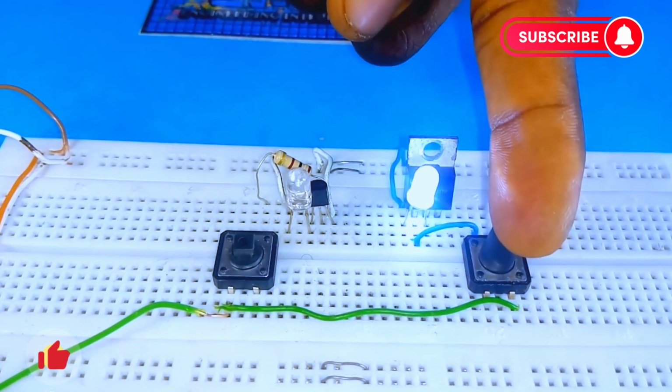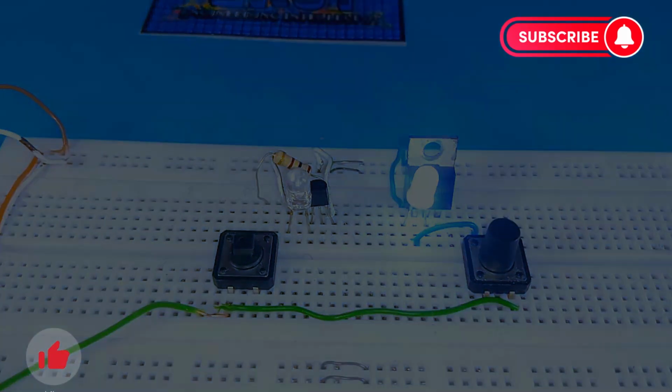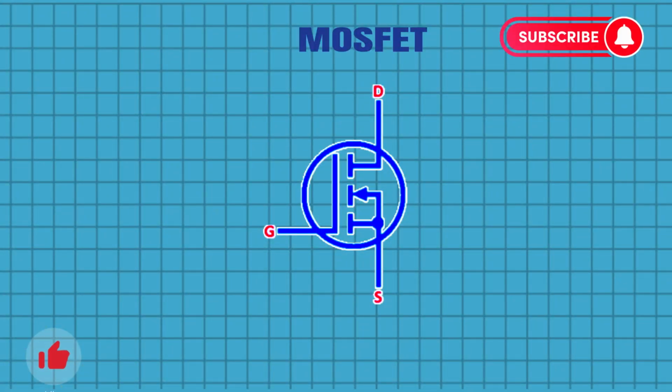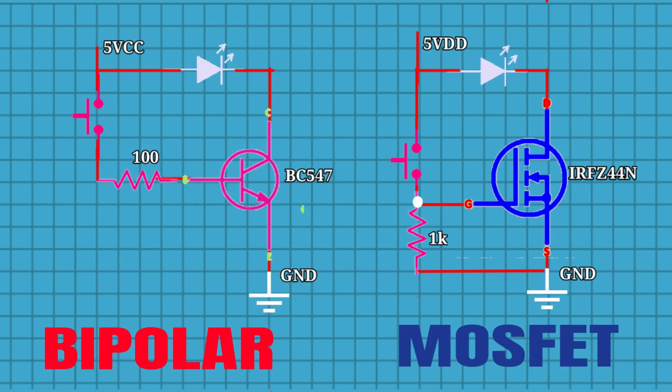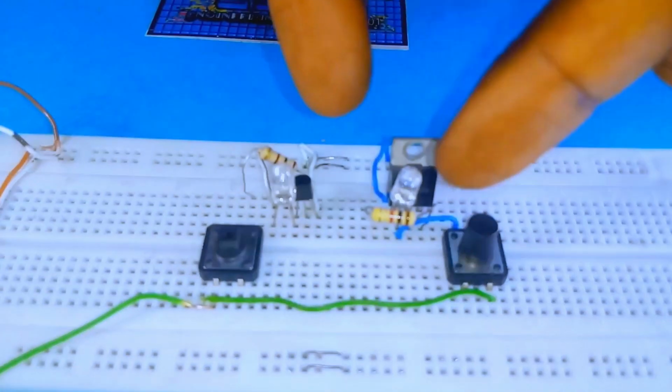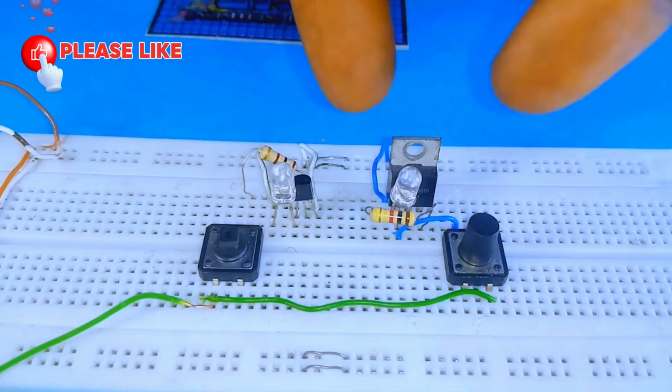The behavior of our MOSFET comes from its physical structure, which causes the behavior of a parasitic capacitor, meaning it is not wanted but inevitable. These capacitor values are very small, in the range of picofarads. So to solve our problem, we just need to add a resistor of around 1K between the gate and the source, and this should help. And now you can see how it works perfectly.